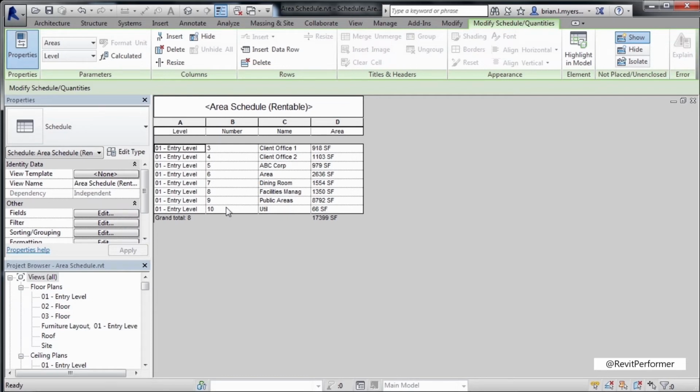And the only way that you can adjust that is if you end up renumbering these areas. Oftentimes, you'll just number them 1, 2, 3, 4, clicking inside of each box and renumbering them. For this example, though, I really don't care about the exact order inside of our model that these areas have. So I'm going to click down here at the number 9, and I'm going to change that to be a number 1. Notice how it reorders those? That's because of that sorting and grouping that we set earlier on. And if we change number 10 to be number 2 and then just click on one side of one of these boxes, we can see it resorts these, but we still have the same total overall square footage for our different areas.